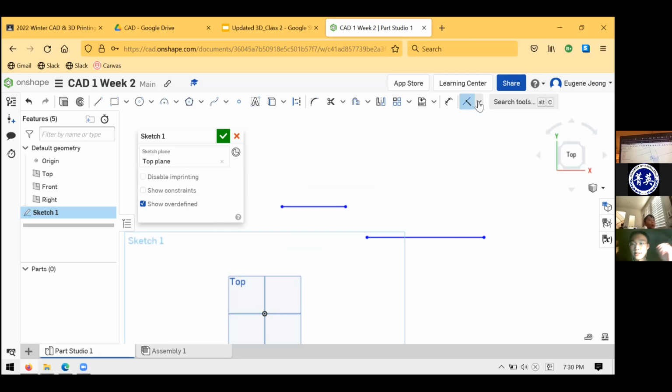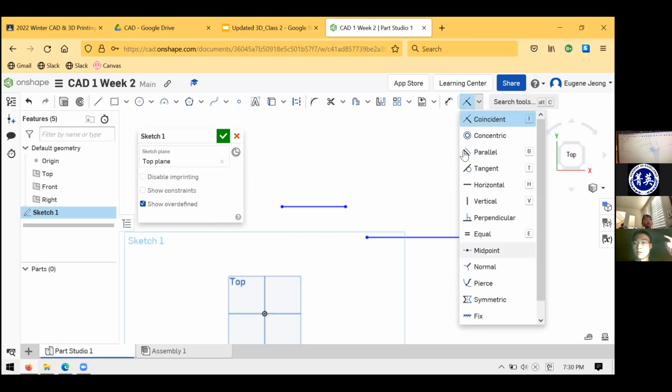The relations tool is the thing that we just went through together with the drop down. Each of these is called a relation. I can't see it anymore. So right now you're back in the 3D workspace. You're no longer working with your sketch, so you can only work with relations. Oh yeah, you need to edit the sketch again.